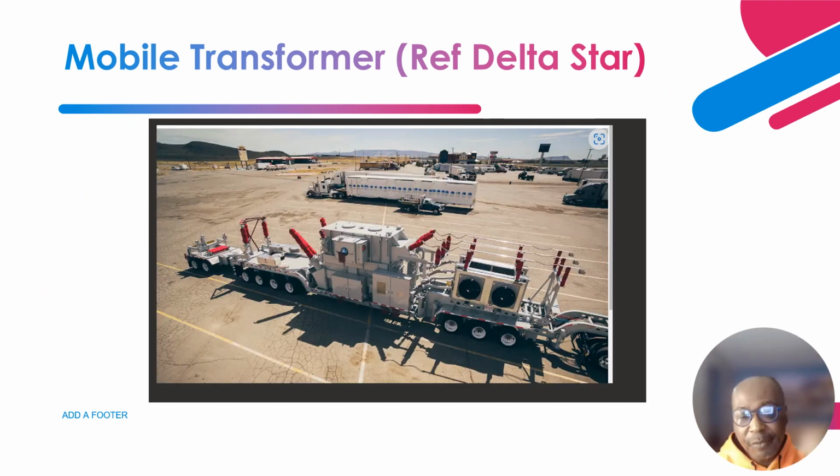Okay, so this is an aerial view, they call it bird's eye view, of this mobile substation. You can see over here disconnect switches, high voltage side of the transformer. This is the mobile transformer, and I indicated that if it doesn't have a high side voltage breaker, then you need a mobile high side breaker. You have to get that to integrate it to the high side.